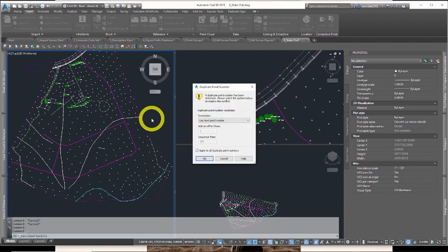You know, this kind of dialog box, when we have many different clients combining a bunch of survey points data, they'll have overlapping numbers. You'll have 2,100s, for example. That happens a lot in the real world. Many surveys from the same firm, let's say, for many years apart, and they didn't have the foresight to make them different point ranges. You just got to be a little creative to keep all the data you want.